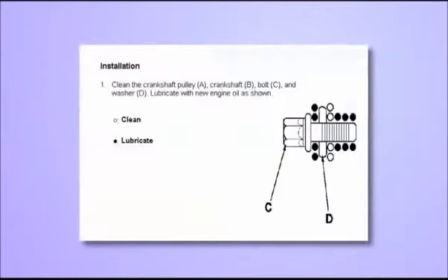By the same token, some fasteners are designed to be installed lubricated. Do not install this type dry or you'll under-tighten the fastener, possibly causing it to work loose.